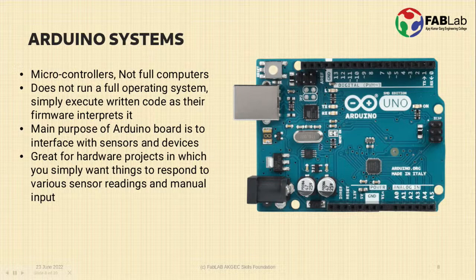You need to be sure whether you really need these components while you are designing your product or your projects, or whether these components are just to help you out in your development process. So in this section, on the left hand side of this Arduino Uno board, we can see that we have one push button. This is a USB A type connector, and this is the DC barrel jack. You can provide the power supply using the adapter through this DC barrel jack.